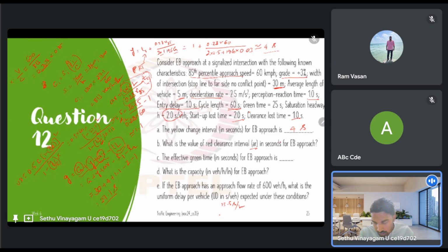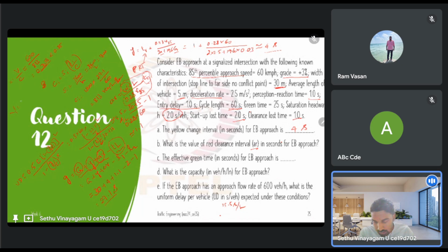See, your yellow interval can have this yellow change interval, small y, and all red. Don't confuse this all red interval with the red interval. The all red interval is given for clearing the vehicles that have already entered the intersection. So you'll have your red, then your green, followed by your yellow and your all red. This all red will be part of the red interval for the other approaches, but for the approach which had green, it will be part of your change interval, y plus AR. That's why when we calculated effective green, we added the all red together with the change interval.